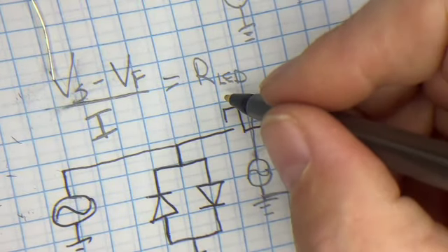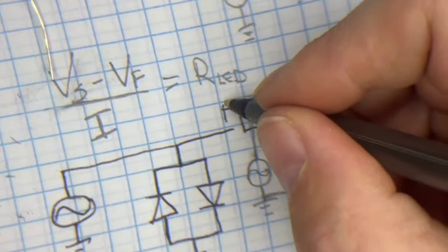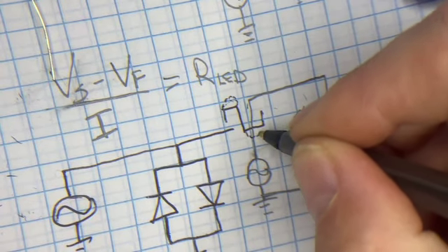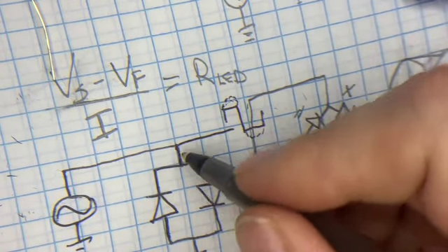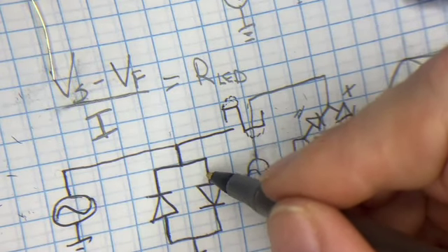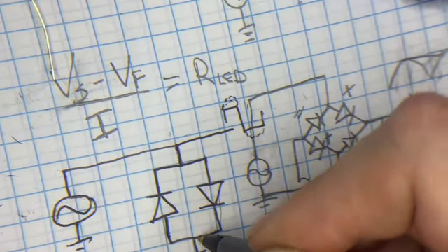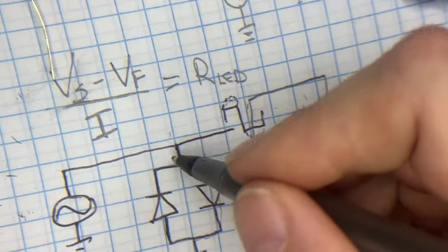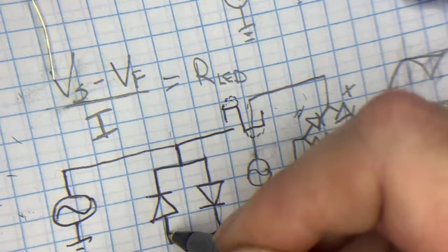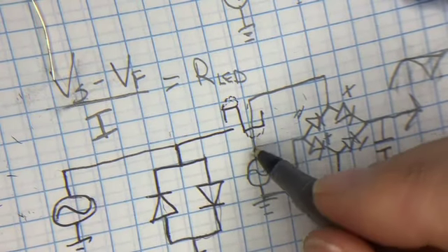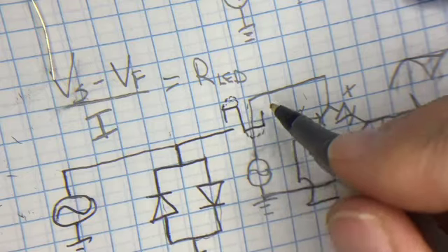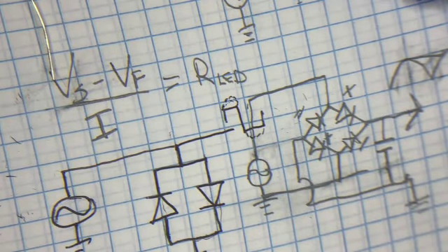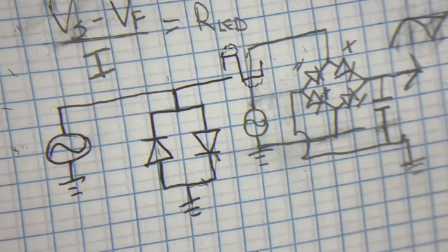Because what will happen is the signal at the top of here and down here are clipped off, because the positive cycle above this forward voltage will go through this diode to ground. The negative cycle, anything below this voltage, goes through this diode to ground. And everything in between just passes through. That's a clipping element. This is the part of the circuit that makes your distortion and overdrive pedals distort and sound overdriven.